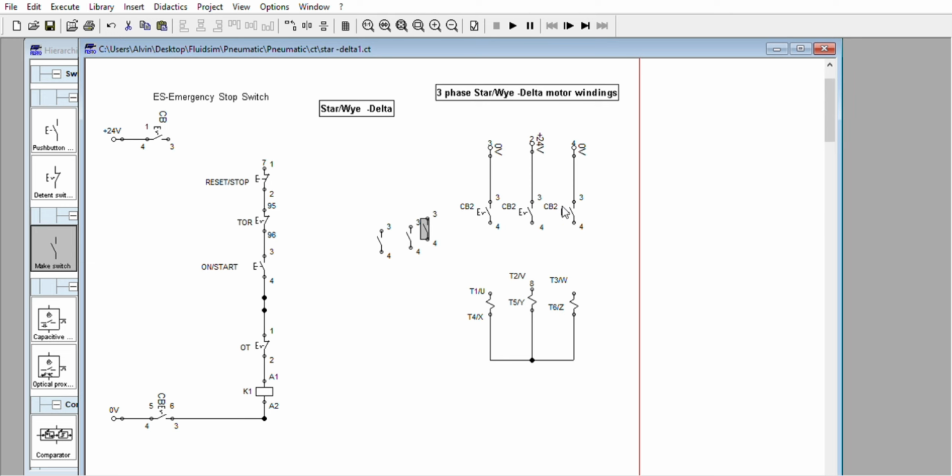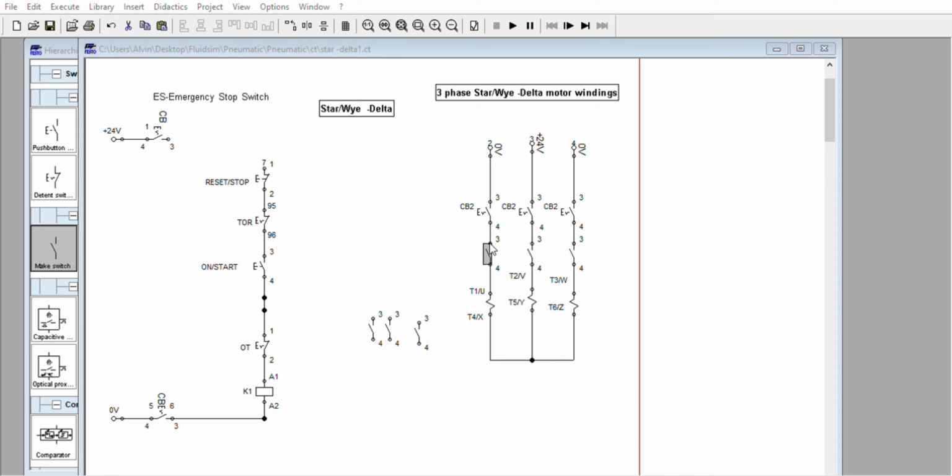Next. So this is one way of creating the control circuit based on the power circuit conditions. So if these 3 lines are connected, they will have the power to the input of the motor. So that means we are going to make this one as contactor number 1, or let's say line contactor. Or this one is the LC.